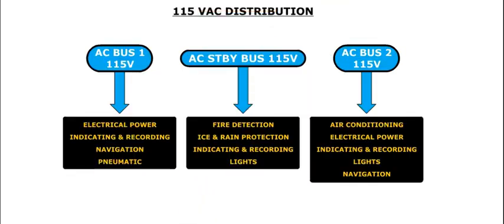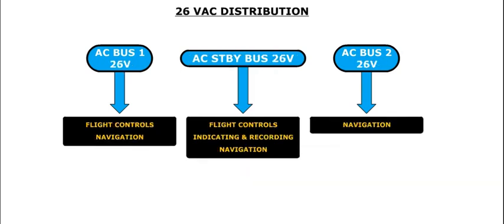The 115-volt AC system supplies AC power to systems such as the smoke detector fans and the digital flight data recorder. The list depicted on the screen identifies the systems using 115-volt AC power. The 26-volt AC system supplies systems such as the flap position indicating system and navigation course and heading selection. The screen depicted here shows all the systems that use 26-volt AC power.